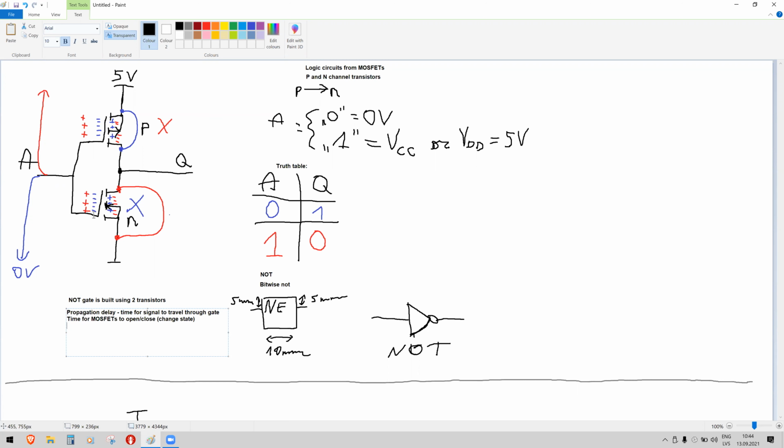And the second thing is, even when the carriers are charged into the gate, we need some time for the charges inside of this bulk material to travel from more distant areas to the gate, to the channel, and to form the channel, and only then can the current start flowing. So it needs some time to happen.